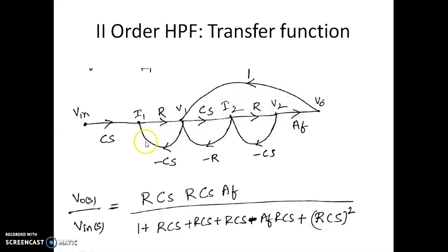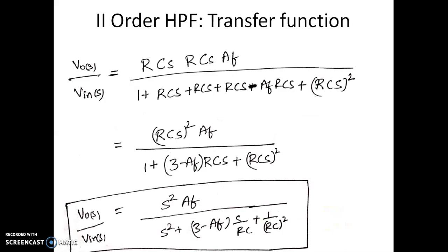This is a positive feedback. The remaining 3 loops are negative feedbacks. You can see that's why it has a plus term. And we have this and this, which are non-touching loops. So 2 non-touching loops. We want to have the gain product of those two non-touching loops. So this will reduce to an equation of this sort.